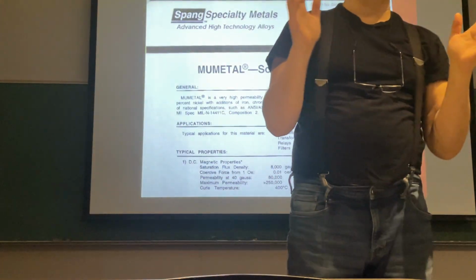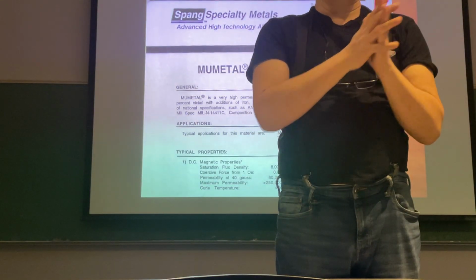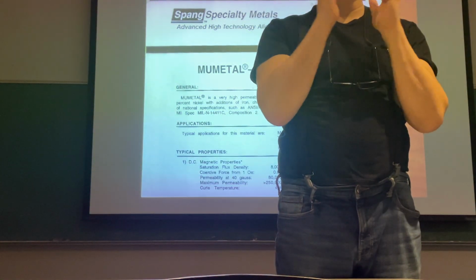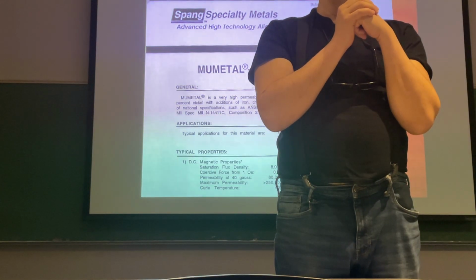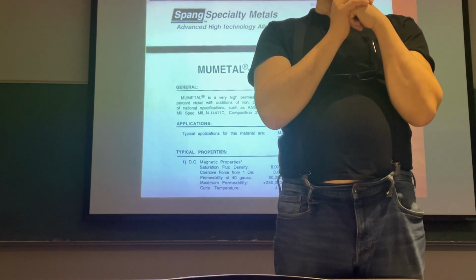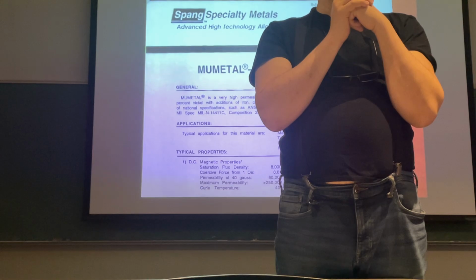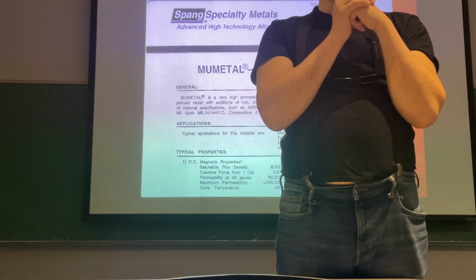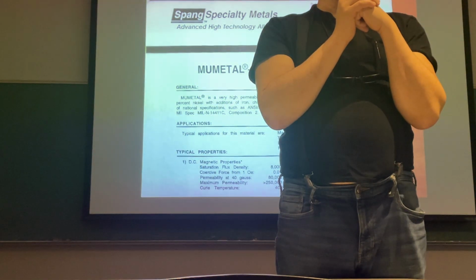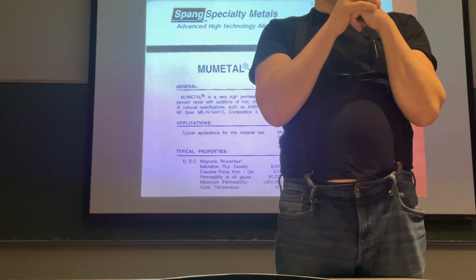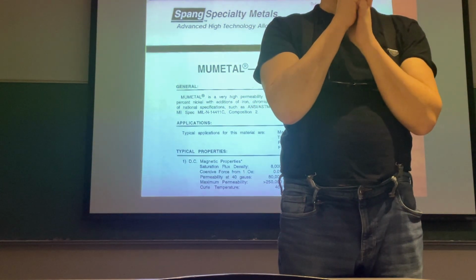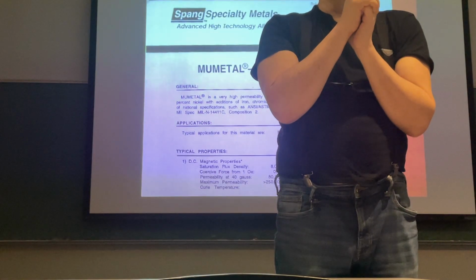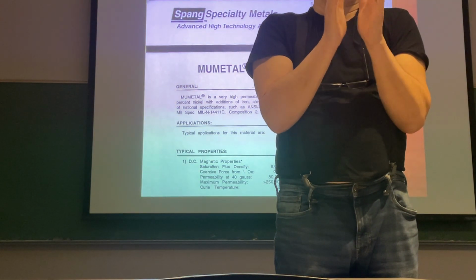Invar is something that has a very, very low expansion, which is nice. One of the lowest expansions of metals. Very, very magnetic stuff too. Then you get another one called Super Invar. God, what is it? Super Invar? Why am I not getting that right? Anyways, that material is bizarre because that one has a negative coefficient of expansion. In other words, when you heat it up in a certain temperature range, it gets smaller.